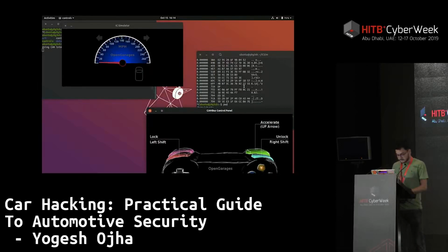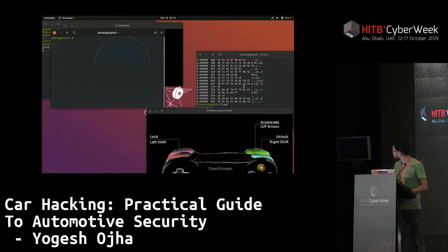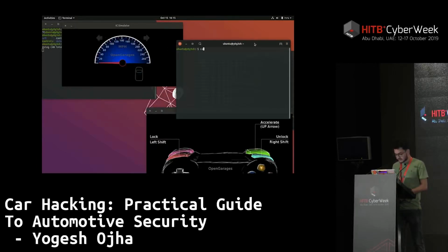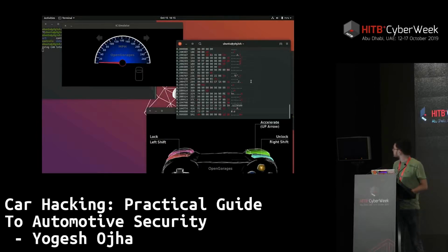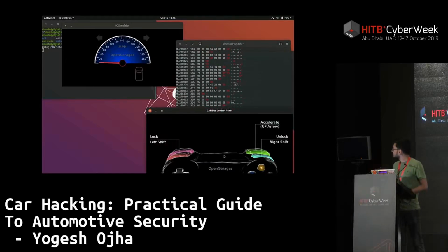Now let's perform the replay attack. To see how exactly the data is being sent, I can always run cansniffer -c vcan0, and you can see all the changes in the data here. If I press left and right, you might see the data change in one of these IDs. Since I already reverse engineered the packets and found this arbitration ID by dividing into one half and the other half the same way, you can spend your time finding out what exactly is the ID that the packet is being sent to.